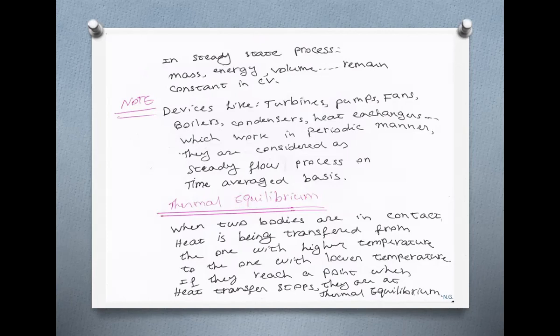That's why we say they are steady flow processes or steady flow devices, but on a time average basis, or steady in the mean. So when you hear the words steady in the mean, or steady on average, then you know you are dealing with devices which work periodically.